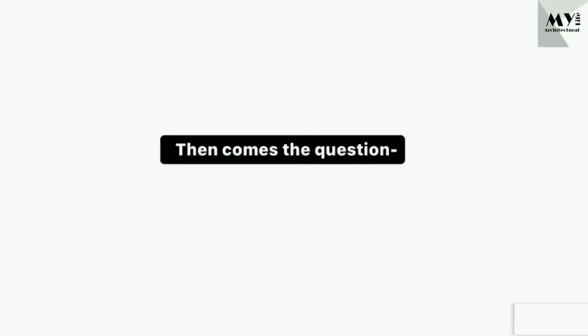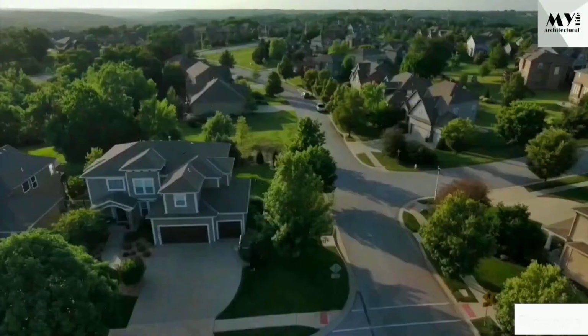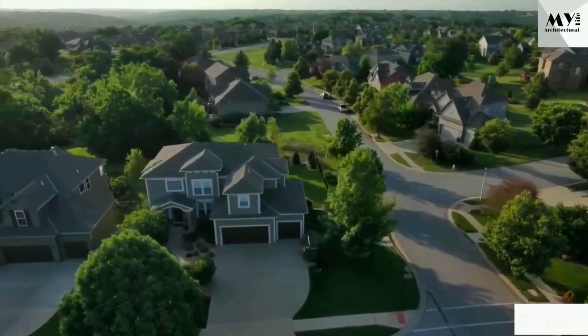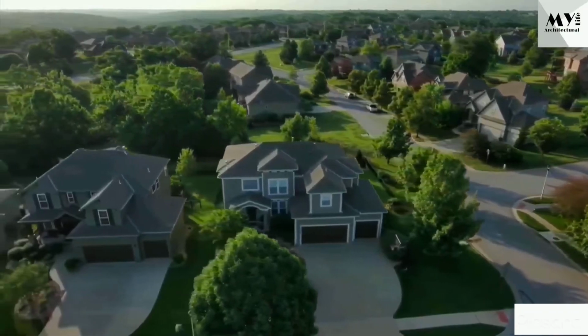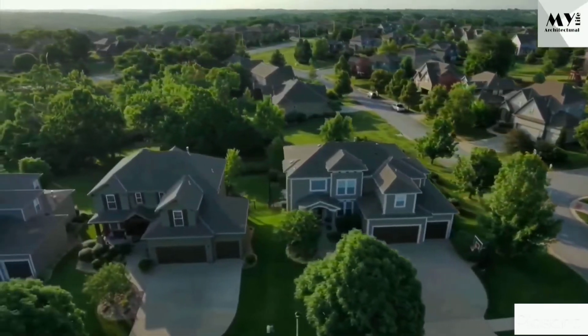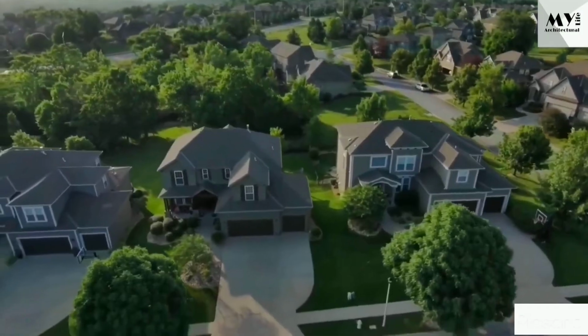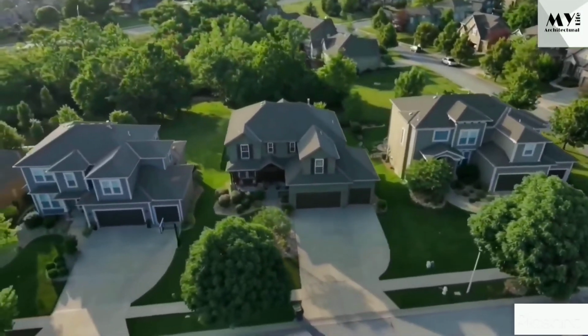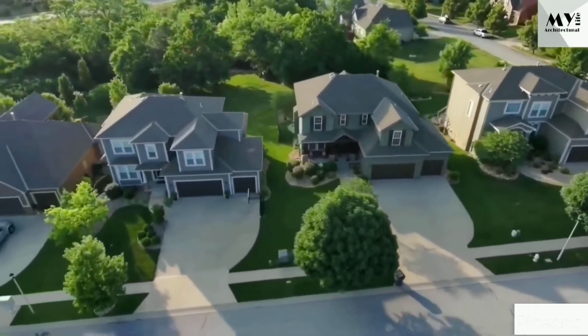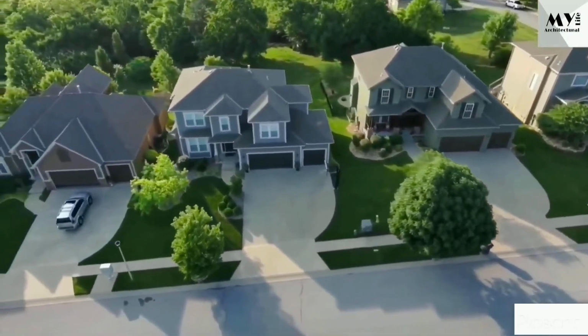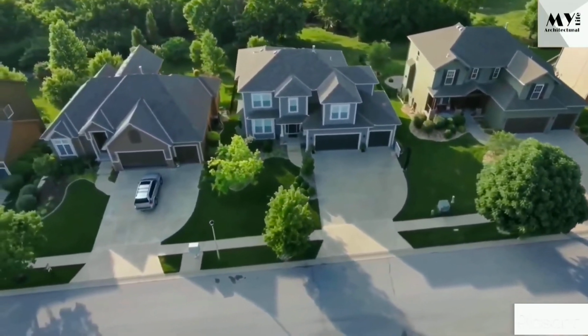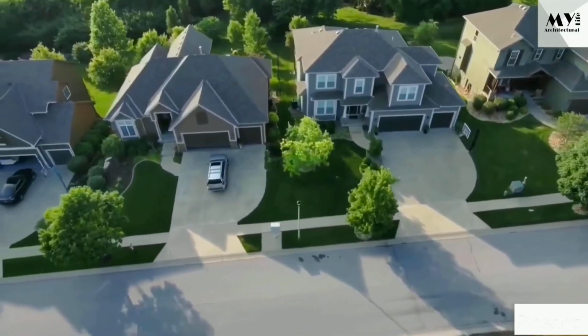So then comes the question, what is site analysis? Site analysis is the initial stage of the architecture and urban design process, dedicated to the study of climate, geography, history, law and infrastructure environment of a specific site. The purpose is to inform us about a site to start our design process, so that our initial design thinking about a site can consider responses to the external conditions.